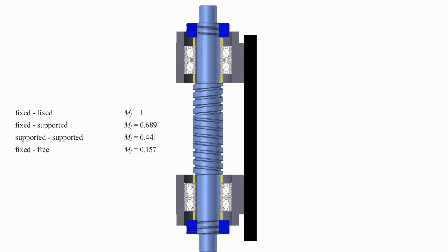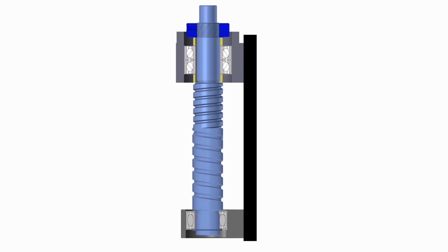But when you use fixed bearing blocks at both sides, then you have to precisely machine the ball screw. Otherwise, the fixed-fixed bearing arrangement will apply excessive compression load on the ball screw. So always try to avoid the fixed-fixed bearing block arrangement, and in general use the fixed float bearing arrangement.